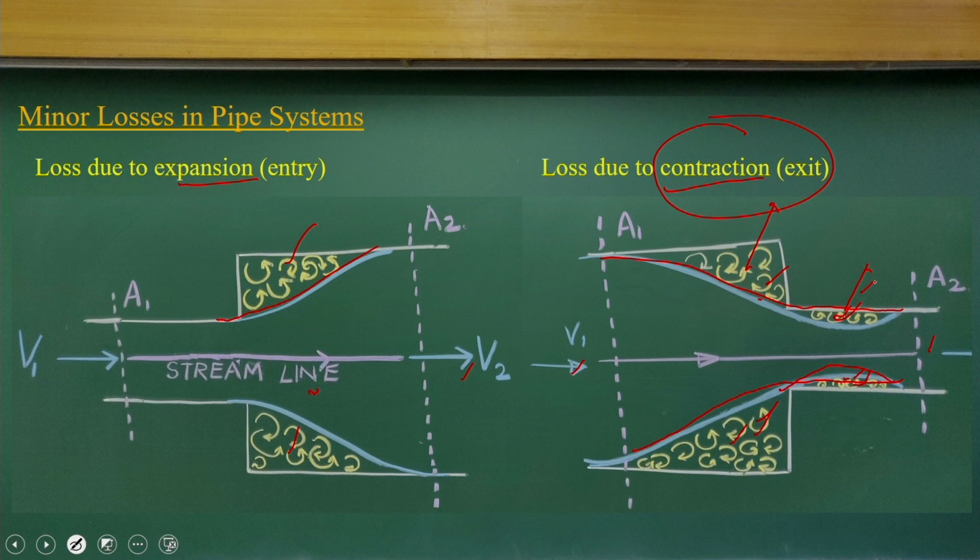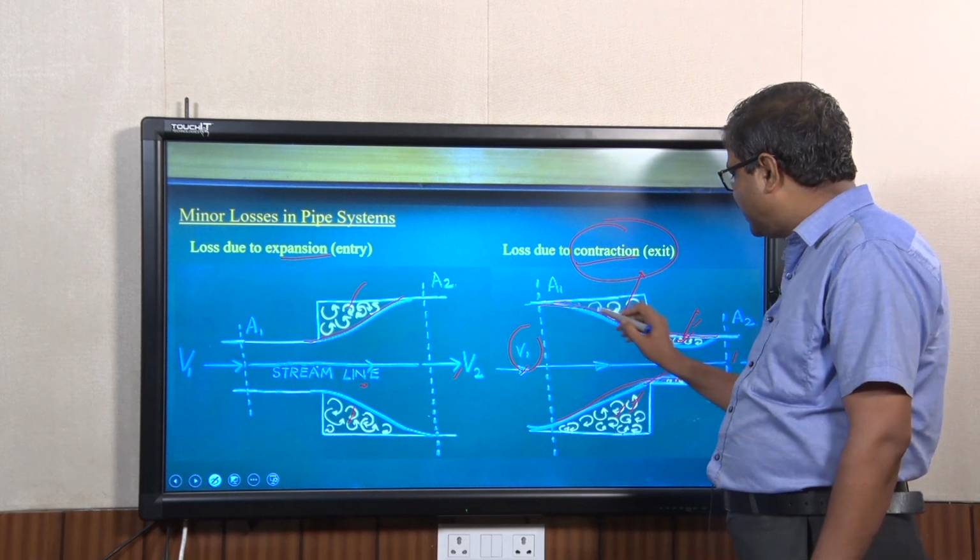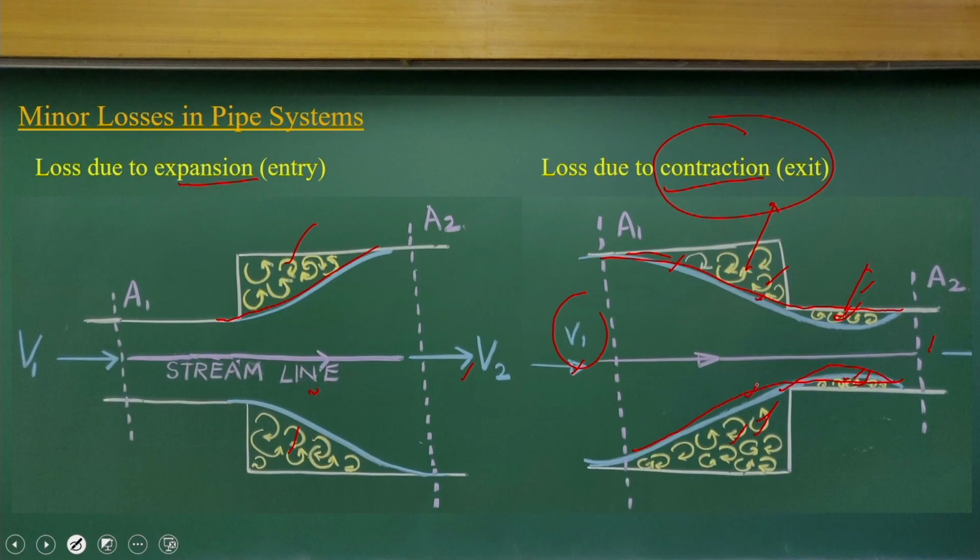And as in a pipe flow, we don't get a constant velocity, there is a fluctuating velocity. The flow varies because water demand varies from winter to monsoon to the summer seasons. So to design exactly the shape of the outer streamlines is very difficult. So mostly we take a trade-off and try to make it as close as possible to have less energy losses. I am just highlighting here to show you the streamlines.